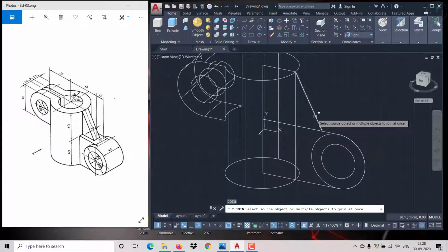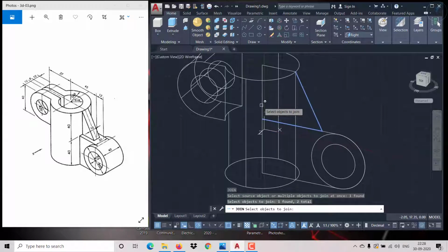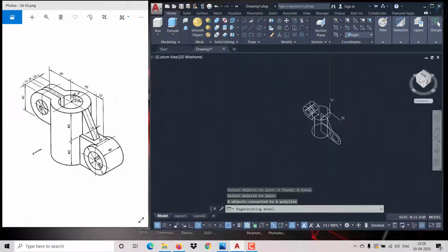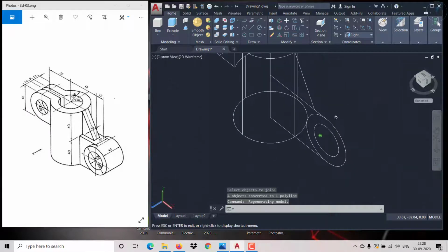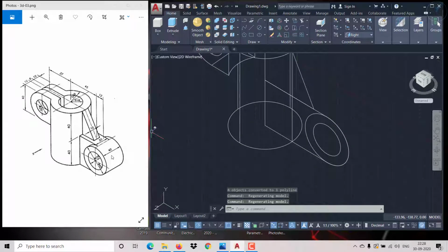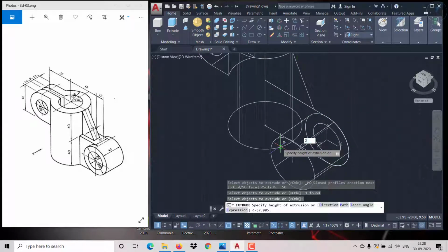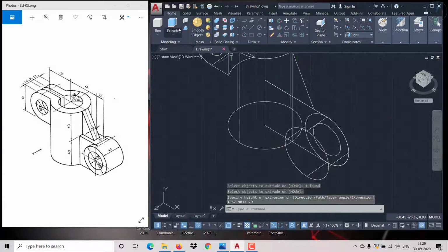So we need to create this triangular shape, a trapezoidal shape, this one over, this one over, and this one over. So the only thing is we need to do the extrusion part. So one by one you can give. So first I am creating this outer that is having an extrusion of 40. So we can give only one side extrusion, that is 20 over here, and then you can go to press pull, rotate it, select the